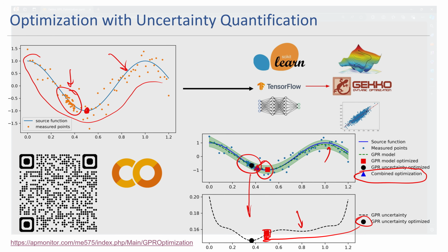You could also create a model predictive control application for a manufacturing process that produces polyethylene in a gas phase reactor. Okay, the MVs are catalyst flow and hydrogen ratio to monomer. The CVs, or controlled variables, are production rate and melt index of the polymer. So it'll go through, and in this case, it just develops a linear model, okay, and then the visualization of that with model predictive control, and it goes through the steps it would take to be able to develop this reactor model.